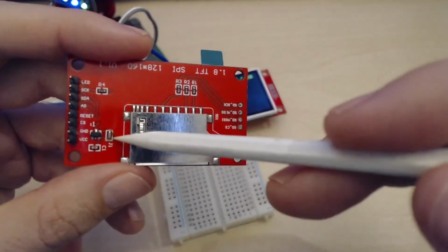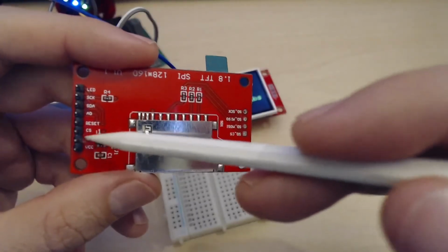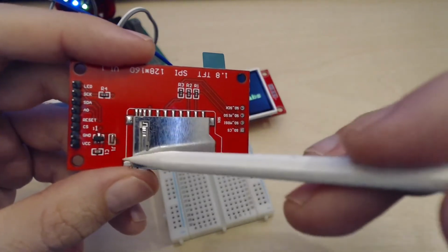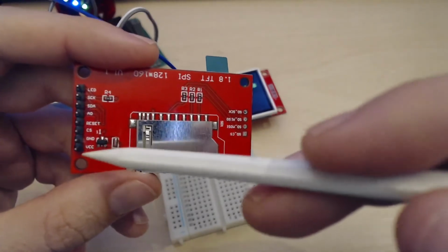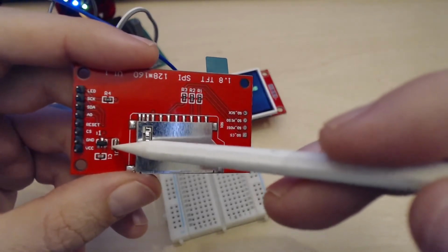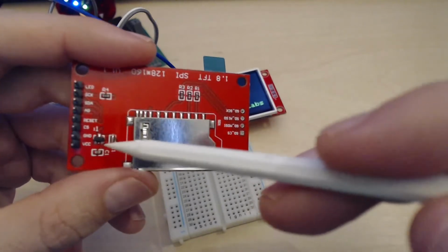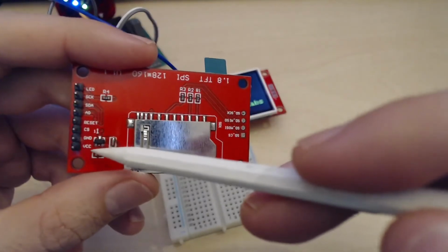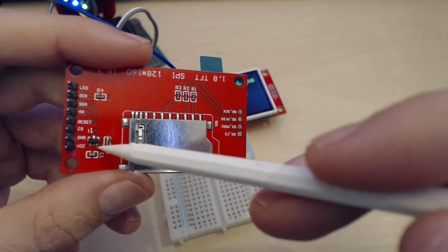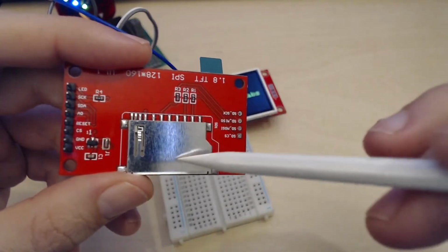Everything will still work. If you short it, it will probably consume less current, because now your supply isn't going through the regulator, and the regulator has a bit of wasted current going on there. So you can just avoid that. But it works both ways. It's not that crucial really. So if you use a 5 volt power supply, you can connect it straight to VCC, and the internal low dropout voltage regulator will be supplying the LCD driver on the module and the SD card as well.